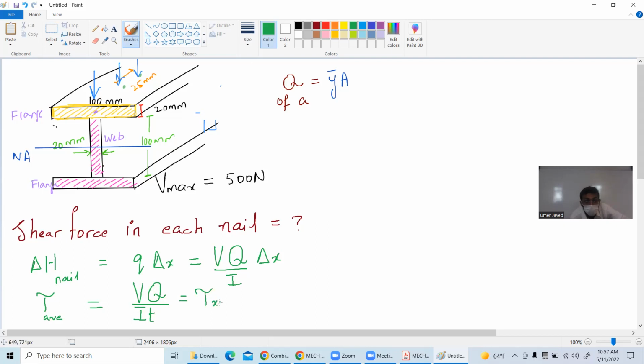Now, there are a lot of students who are saying, like, come on. You said average shear stress is equal to V over A. Load is being applied. What is shear stress? You throw that chunk away. V over A. Why are you teaching us this? I told you longitudinal shear, because at the end of the day, between each layer there is longitudinal shear. I want to talk about this layer. I'm fed up with talking about the whole cross section in an average shear in this direction. So for that, I need average shear in that longitudinal layer.